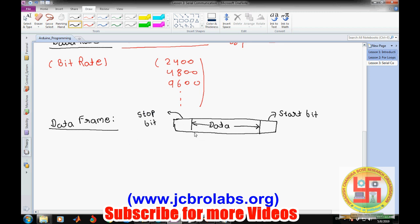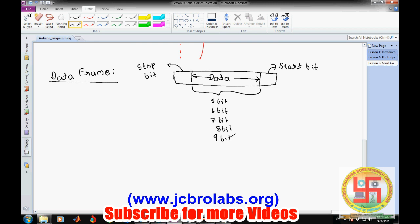And in between, in this data packet, 5 bit, 6 bit, 7 bit or 8 bit of data can be transmitted, or I think 9 bit of data can be transmitted over a channel. So it has to be specified prior to using this particular communication. It has to be specified to the microcontroller, in which mode and how many bits of data we are going to transmit over the channel. But you don't have to worry about all these things in Arduino.